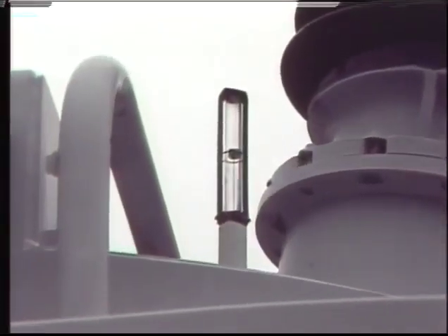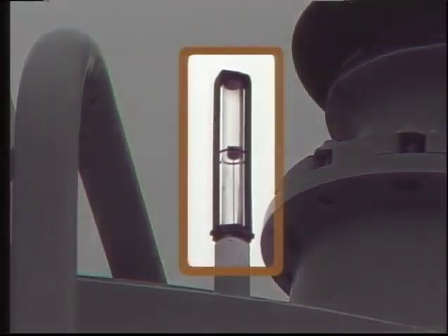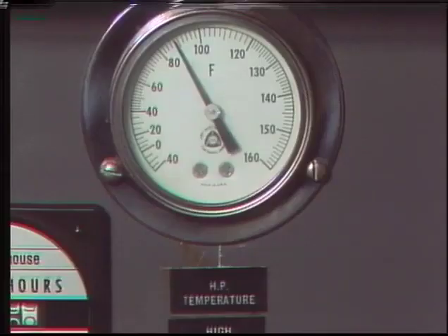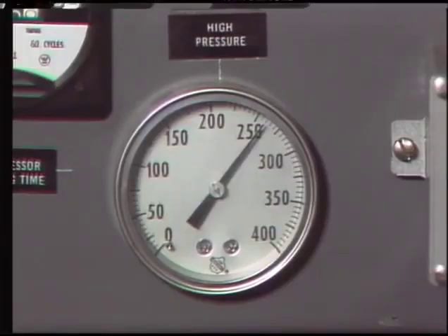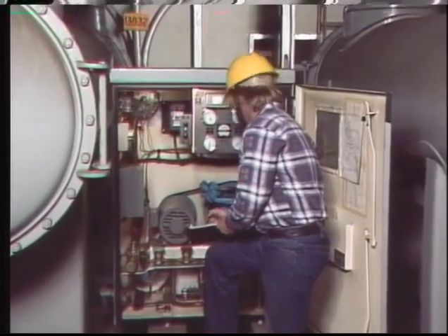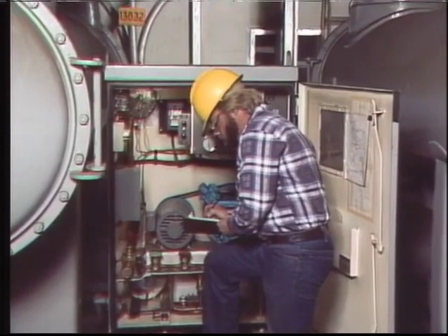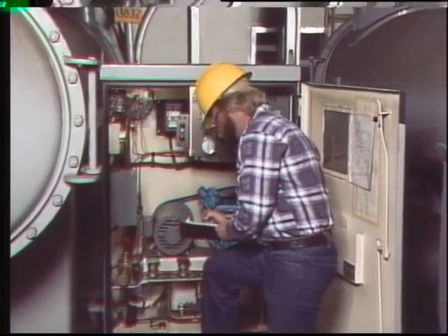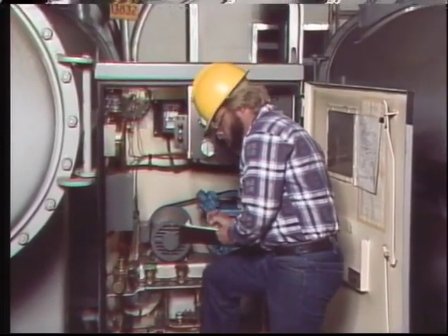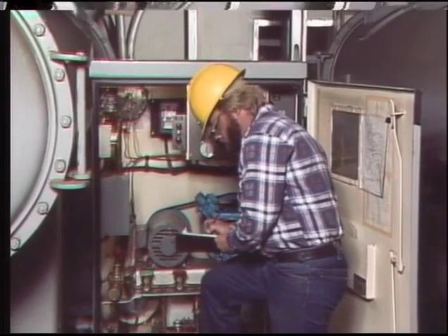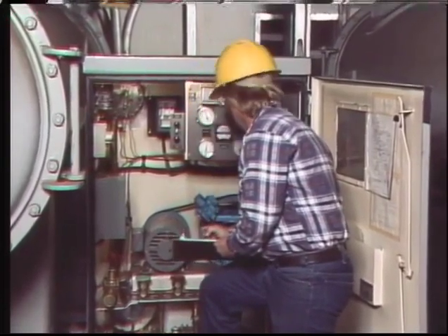Other indications that should be checked and noted can include gauge readings, such as an oil level indication, temperature indications, and pressure indications. It's important to document your observations thoroughly and accurately. Such records help to track the status and performance of a breaker and identify problems before they become serious. Routine status checks are a key step in preventing breaker failures.